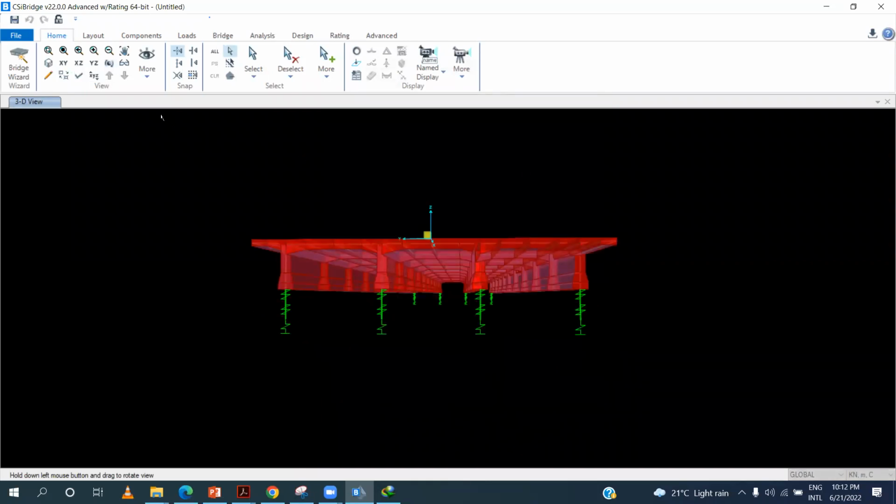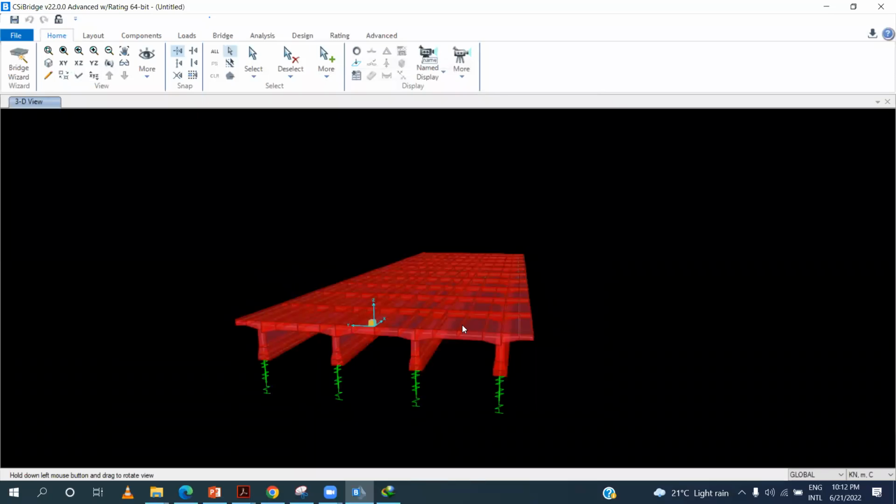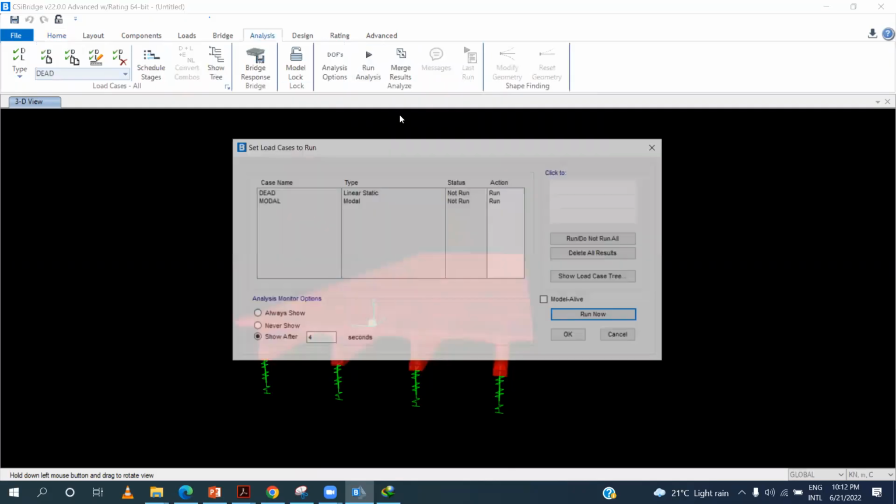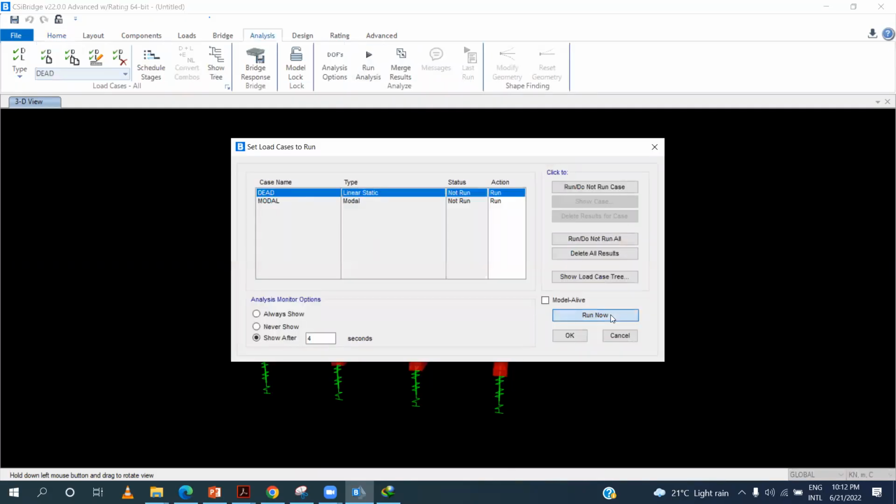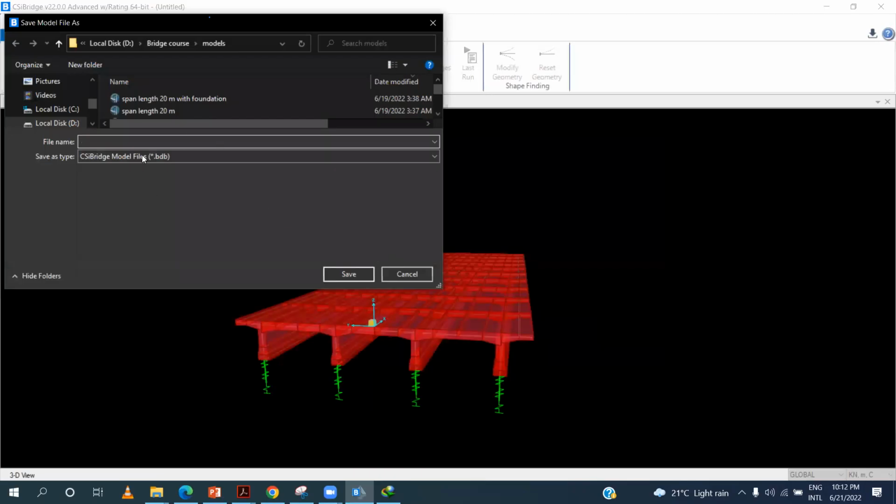It will be the same for the spine model and the area model, but the difference is in the analysis. If you model it as an area model, it will give you the forces for each girder separately when you perform analysis. So let me perform a dead load analysis. For example, I perform a dead load analysis. This is project one.